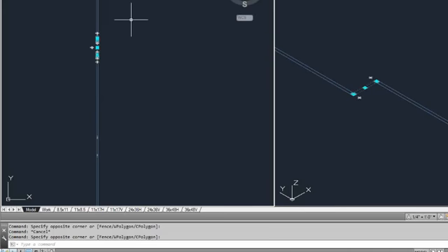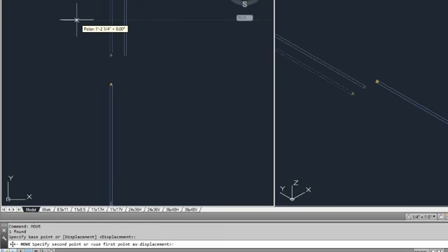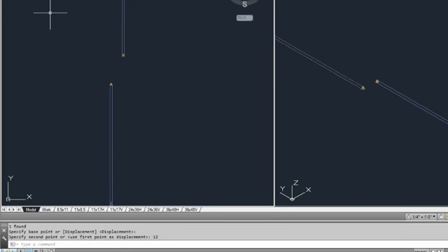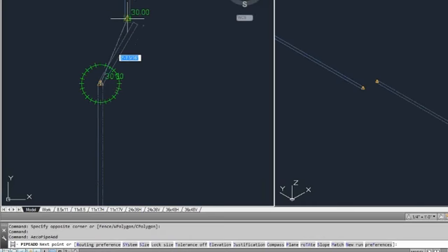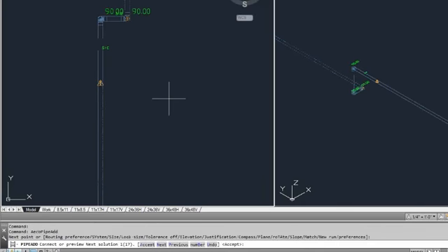the best way to do that is, so if I had a situation here where this was off to the side, maybe 12 inches, the best way to do that is just let AutoCAD MEP choose what it needs to do. So when I selected those together, it's giving me an option of how to connect them. If I look at the command line, we can see that it's saying connect or preview the next solution 1 out of 17. So it's giving me 17 different options on how to connect those.